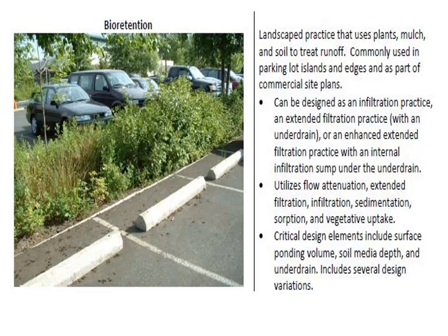It's a common practice in places that are trying to be green to have strips of vegetated area next to parking lots, and to slope the parking lot so that it goes into this vegetated area. Bioretention means that you're holding on to the water, and at the same time you're filtering out salts, oils, grease, and the nutrients that would be problematic if it got into the watershed.